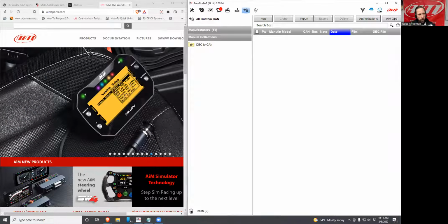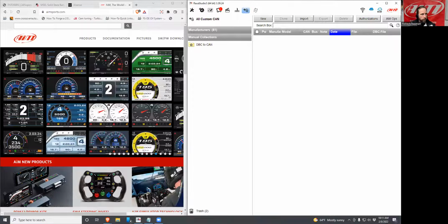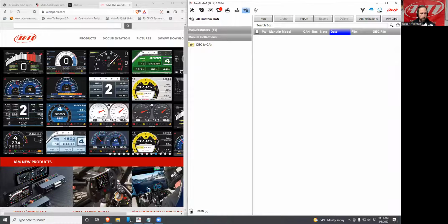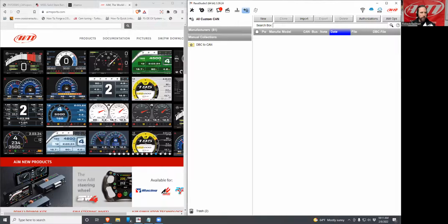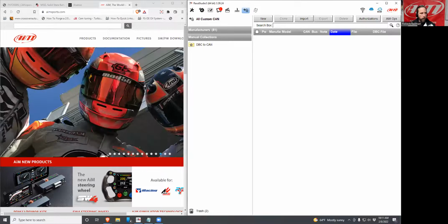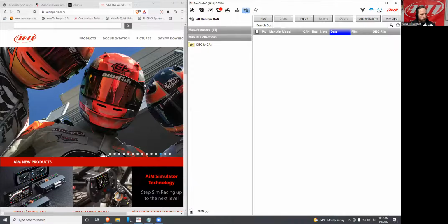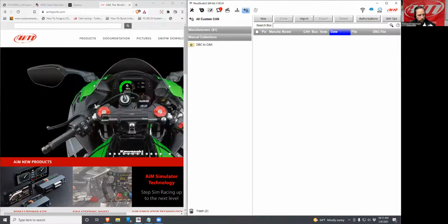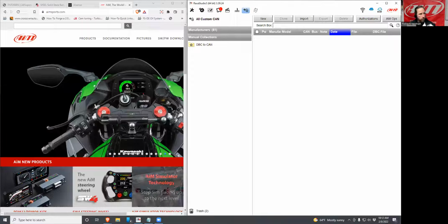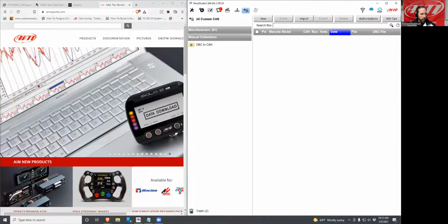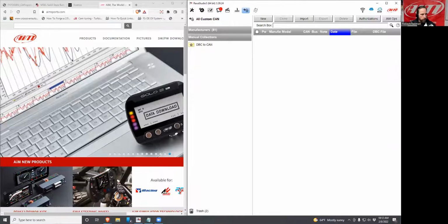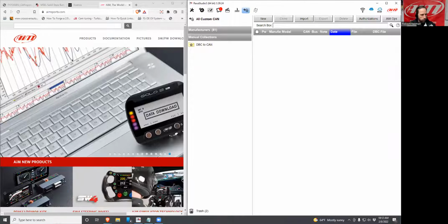So if you remember when we did the webinar with Jeff Wasilico, we talked a lot about bus speed and how getting all the devices working requires that they have the same bus speed, or you will shut down the CAN bus. It will no longer function, and most of the time we don't get any type of lasting faults. So setting the wrong bus speed on a sniffer or a device will shut it down temporarily. You remove the offending product and reboot it, and everything works a-okay.